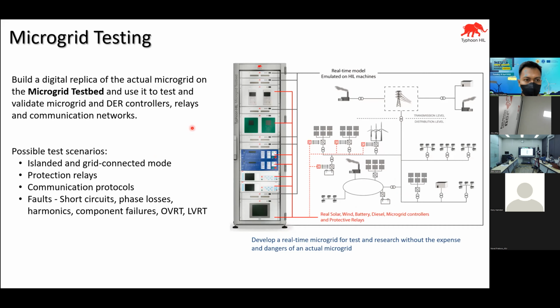Now, the main microgrid controller, or the hybrid controller, we have different names for it, but the top level controller must be able to respond to different scenarios. Whether it is islanded, or connected to the grid and suddenly there is a disconnection from the grid, it must be able to perform in islanded mode. How to make one of the energy resources form the grid rather than follow the grid. It must be able to